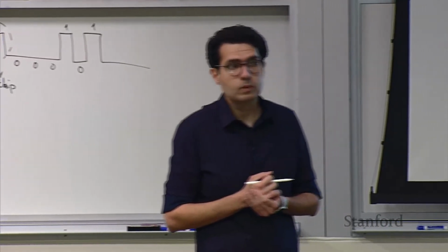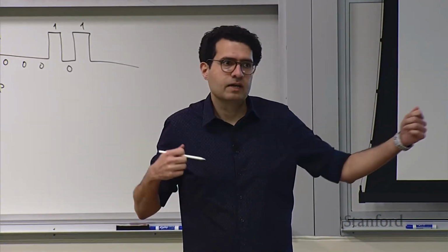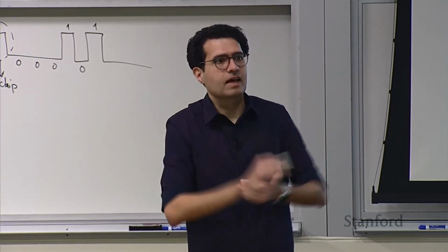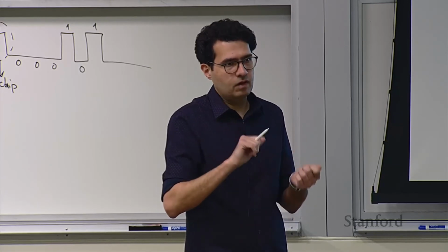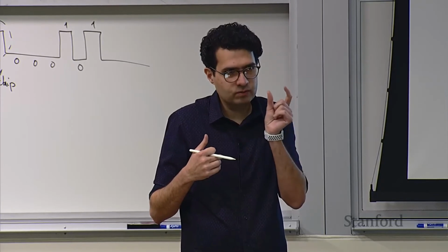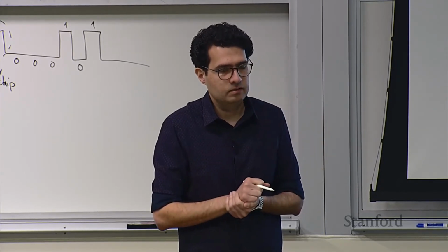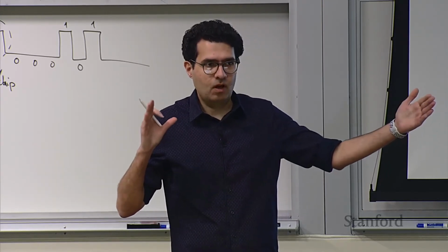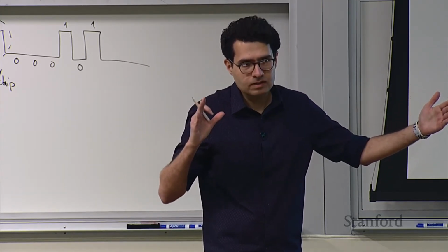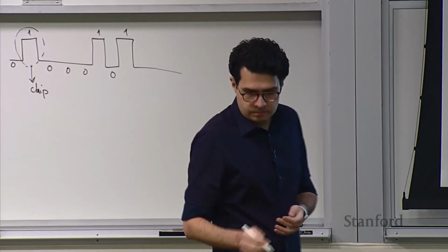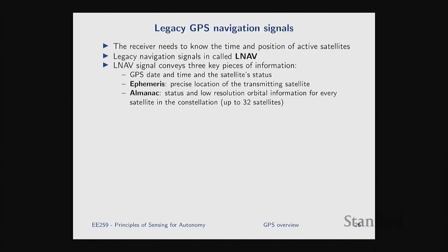Okay, so the fact that it's just long helps them in the cases where the signal is very weak. Then you can just integrate or acquire a longer piece of this code to boost your SNR, and then you do acquisition. So they have this trade-off knob: when the signal is strong, just do very short acquisitions and do ranging with that. When the signal is very weak, just capture a longer section of this long signal and then do ranging with that, if it makes sense. Okay, great question.